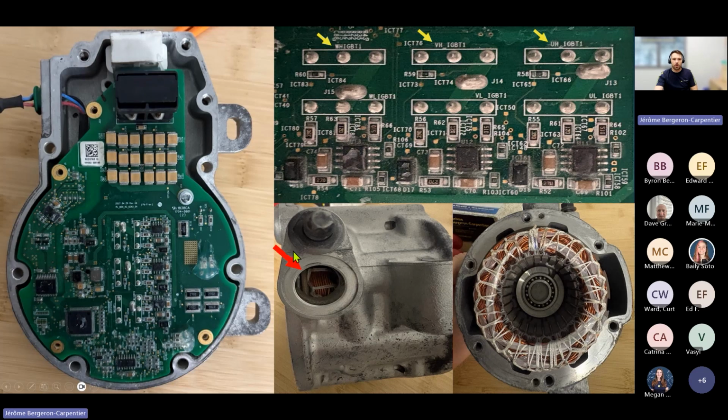We're going to put that PCB board next to the low side port on the compressor itself. So we know that normally it's going to be gas, but quite cold gas, that's going to be sucked into the compressor by the low side port. So in that case, that low side will be cooling down that PCB board with the inverter.